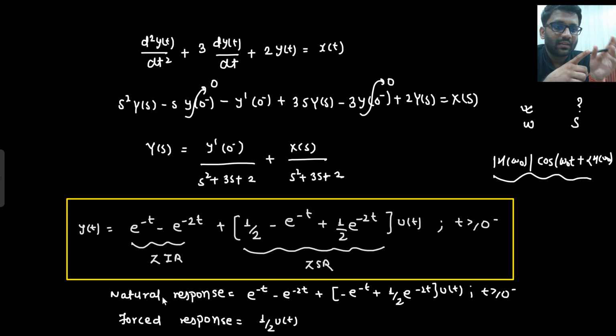Mostly you can only comment on what kind of filter it is, what kind of frequencies it will pass. But if you talk about the system in S domain, if you just know the poles and the ROC, then you will get to know whether it is causal or stable, or if you want to make it anti-causal, then what the ROC should be, and all these kinds of things you will be able to comment on. So that's why we moved from omega domain to S domain.